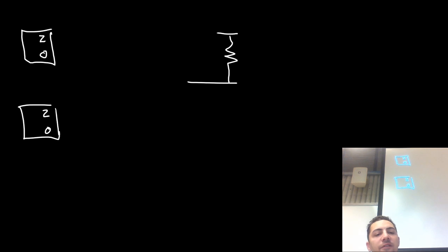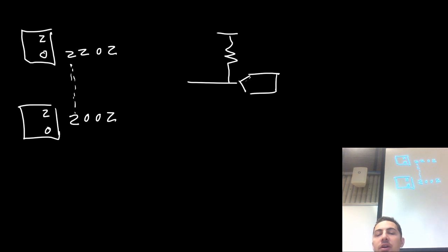So let's just say that the first one outputs Z, Z, 0, Z. That's the number 13. They wanted to do 1, 1, 0, 1. Now let's also look at this one, Z, 0, 0, Z. They tried to transmit at the same time. First off, nothing blows up because we're not shoving 5 volts into any of the zeros. Okay? But what happens when you take 2 Z's and you output them? What appears on this output node here?